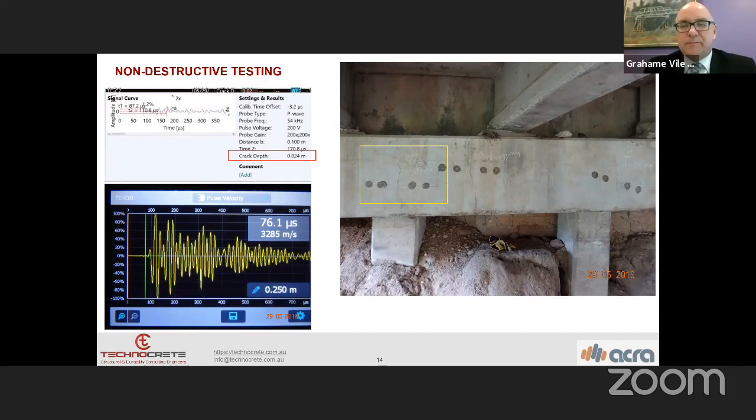No worries. Interesting questions. Thank you. The next slide is what I have included for the crack depth. As you can see, the same case study, on the right-hand side, the photo of the actual structure, you can see C7 means crack 7, depth 24, C8 depth 57, and then C11 depth is 34 millimeters.